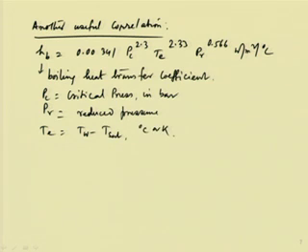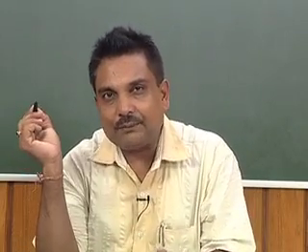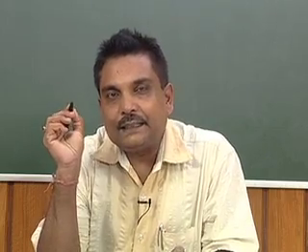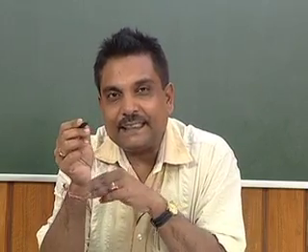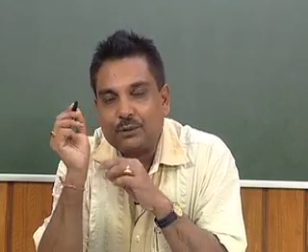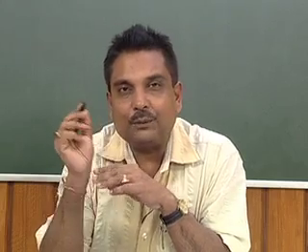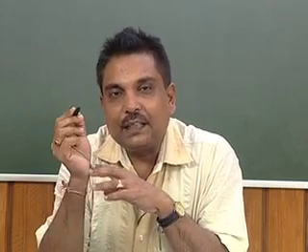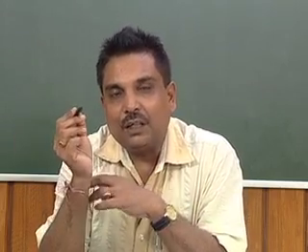Okay. So, in addition to this, there is another important thing that we should know, that is called critical heat flux. We discussed in the last lecture that there is a critical heat flux. If we move beyond it, that is the critical point, more or less the metastable point, after which film boiling becomes important.